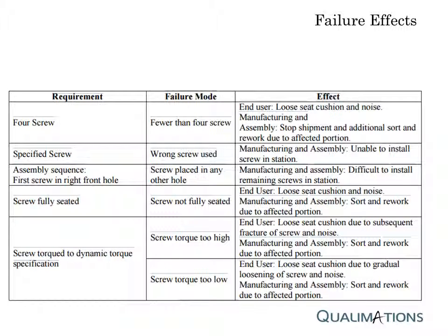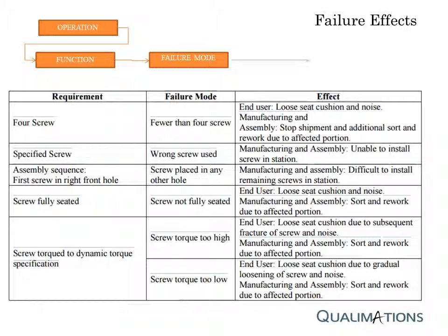Potential effects of failure are defined as the effects of the failure mode as perceived by the customer. The effects of the failure should be described in terms of what the customer might notice or experience, remembering that the customer may be an internal customer as well as the ultimate end user. The customer in this context could be the next operation, subsequent operations or locations, the dealer, and/or the vehicle owner.